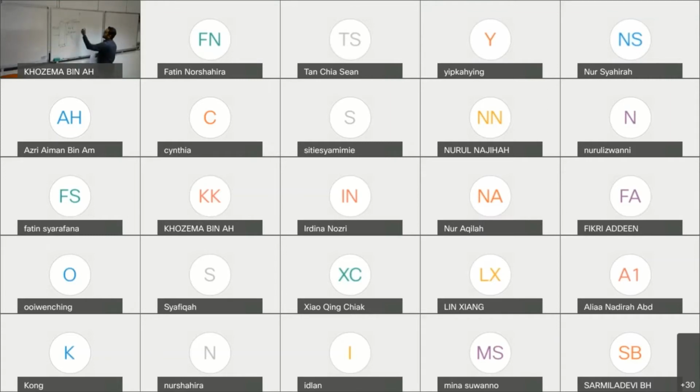So again, let us write our equation. Q is equal to... from this point on, I prefer to use this equation. It is easier for me to use this equation. So I know the value of K is given as 385 watt per meter degree Celsius. A is 300 times 200.